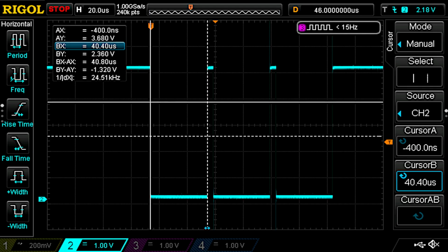About 40 microseconds to do both the modulus and division. Instruction clock should be around 400 nanoseconds, so around 100 instruction clocks. Not near as bad as I was expecting. So could do 5 digits and still have time to spare in the millisecond.